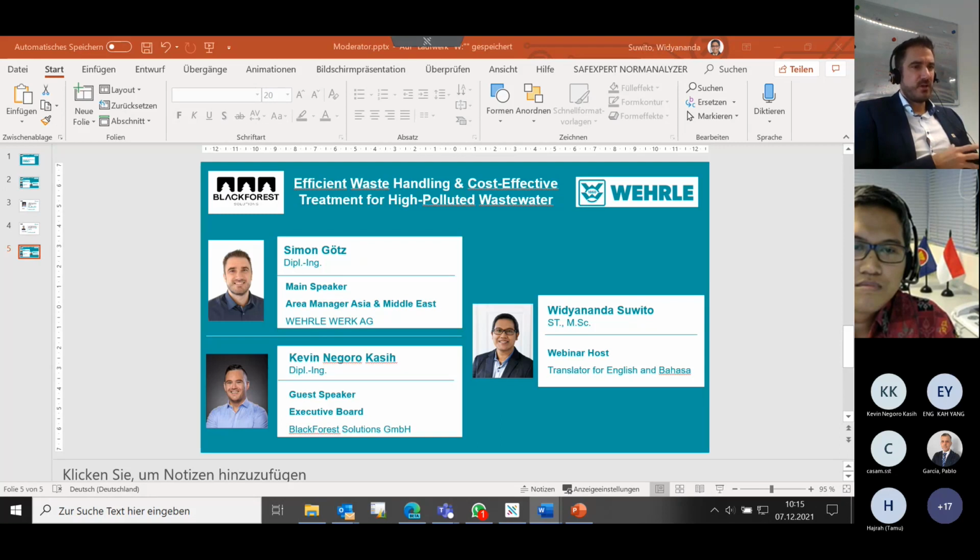We accept it, we are okay with that, but usually they have to cope with a slightly, or sometimes even drastically, reduced cleaning efficiency. That means maybe they need to do a chemical cleaning for a UF membrane every 4 weeks instead of every 6 or 7 weeks, because the efficiency of the cleaner is reduced. But to answer it clearly, yes, it's possible to use local chemicals.